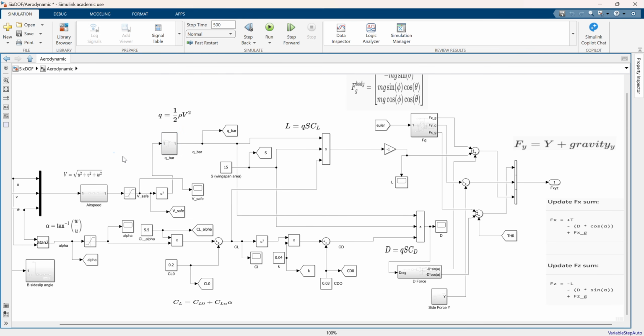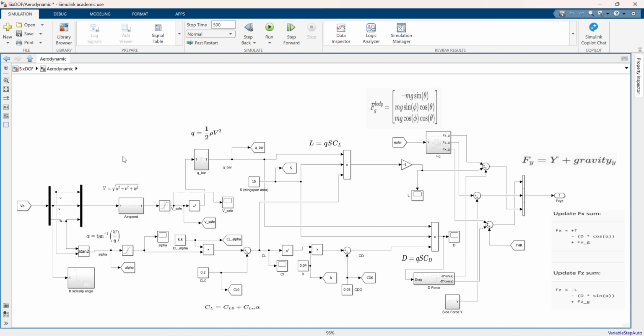And this is mainly slowly what you will see going towards medium fidelity: you will go and replace all the relevant constants, which we are going to talk about later, one by one with lookup tables. Lookup tables would come from real flight data. Things like CL alpha, for instance, CL0, all these will become a function of some other variable or maybe multiple variables. That's where you increase fidelity, right?